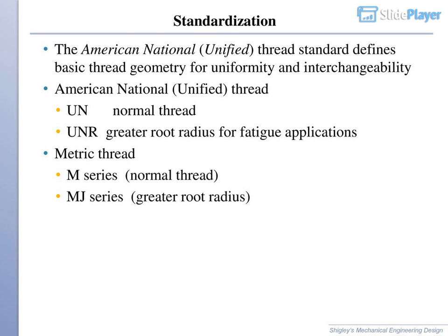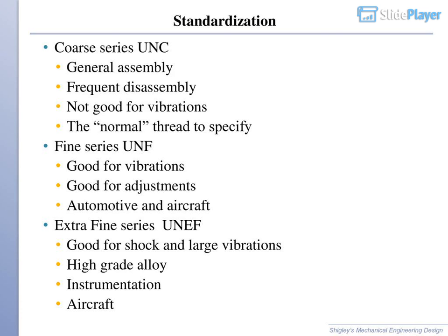Coarse series UNC: general assembly, frequent disassembly. Not good for vibrations. The normal thread to specify is fine series UNF: good for vibrations, good for adjustments, used in automotive and aircraft. Extra fine series UNEF: good for shock and large vibrations, high-grade alloy, instrumentation, aircraft.